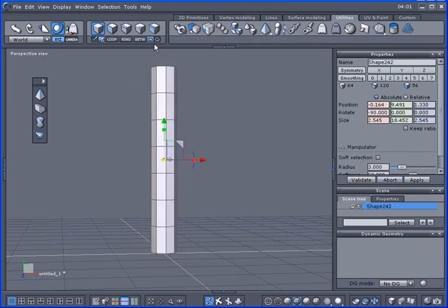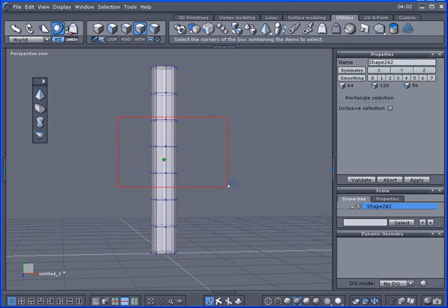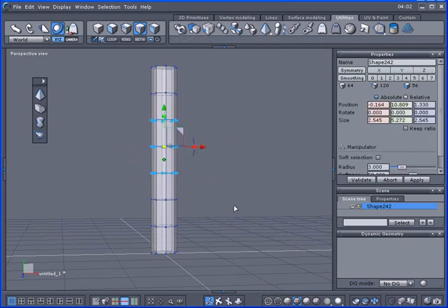One little tip you can do is select a selection of points here. So I'm going to select here. I'm going to go ahead and turn on the transparency here. Since I have the transparency on, when I right click and make a selection, this will select the points all the way around it instead of just the ones facing forward.